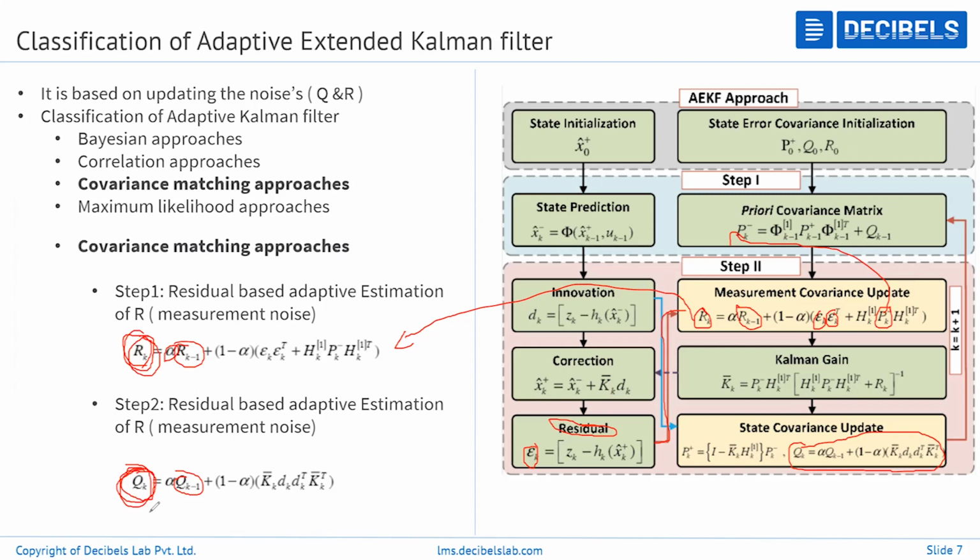So in some scenarios, with a sensor, let's say a current sensor, I have seen many current sensor profiles. In that, if I am measuring from 0 to 5 amps, the error will be like 1%. I'm just taking a random example. And if I'm measuring from 10 to 15 amps, the error will be like 1.5%.